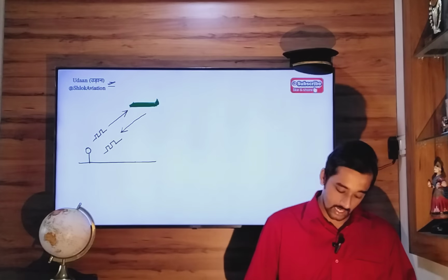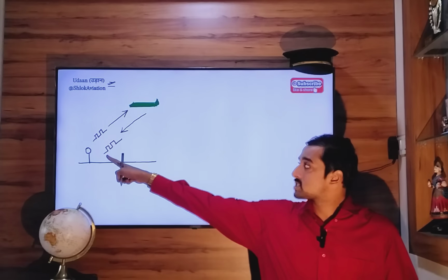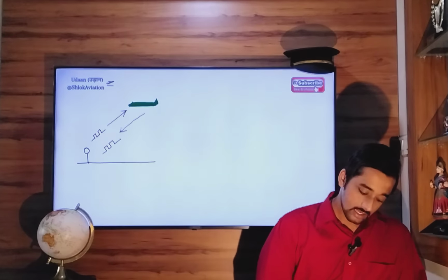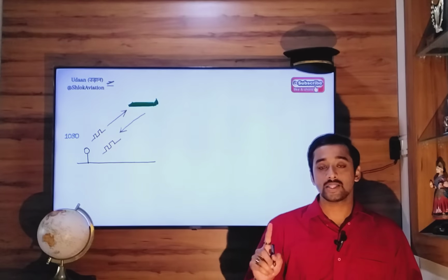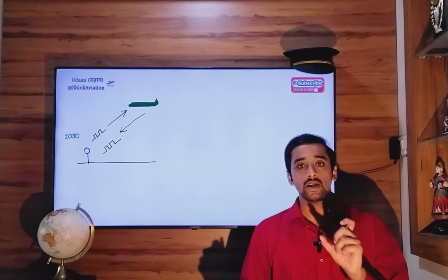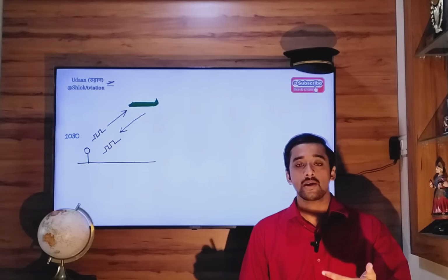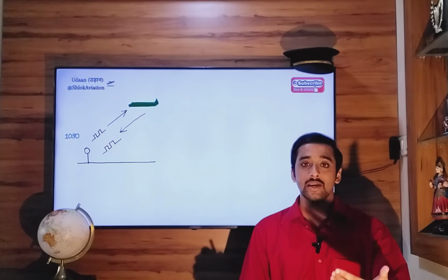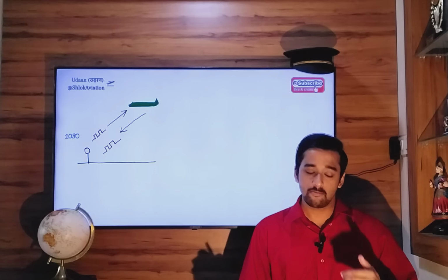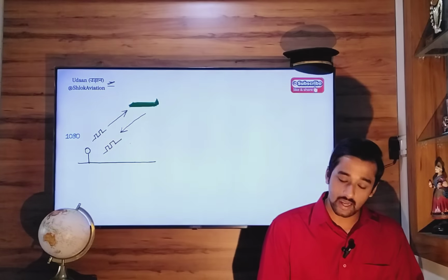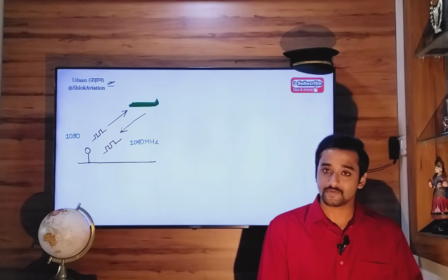But there is a twist. I'll explain that to you. Now, the frequency at which this pulse is transmitted towards the aircraft is always 1030 megahertz. When this pulse strikes the aircraft, the transponder in aircraft will reply to this pulse. It will send its own unique information, or unique pulse. This reply pulse will be sent back at a frequency of 1090 megahertz.